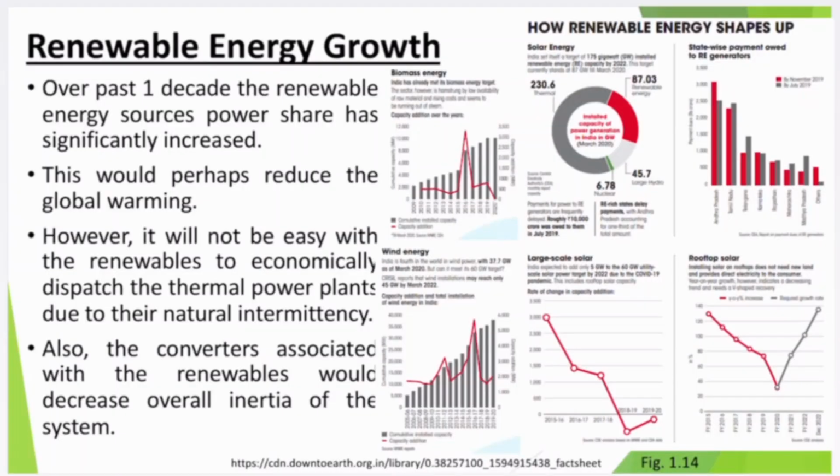This is because those huge generators do carry inertia within them. That means they do store some energy within themselves. As and when there is an oscillation of requirement, they provide that inertial power. Okay? And hence we don't realize any mismatch between my requirement and its availability. But in the case of renewable energy, wind to some extent is fine, but especially solar, there is no rotational part. If you do not have a rotational part, then you do not have inertia, energy or power. And because of that there is a lot of challenge.